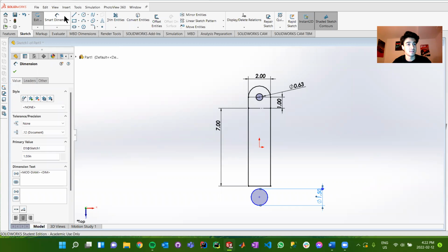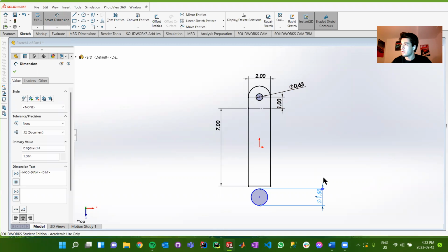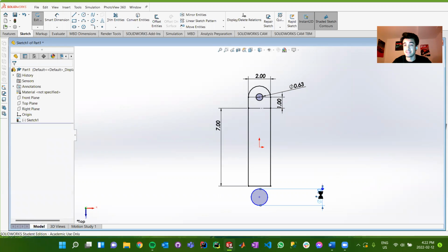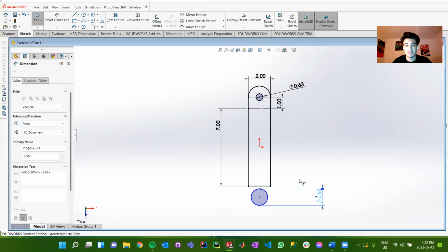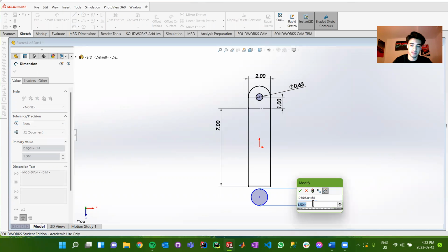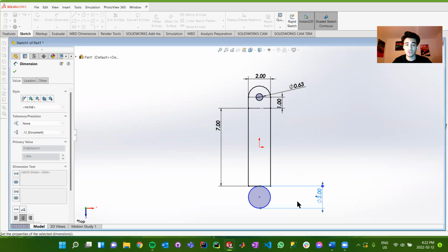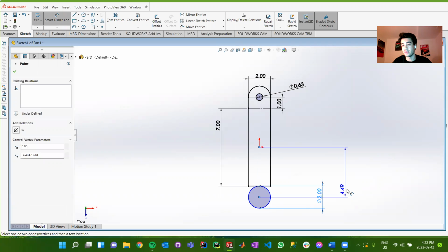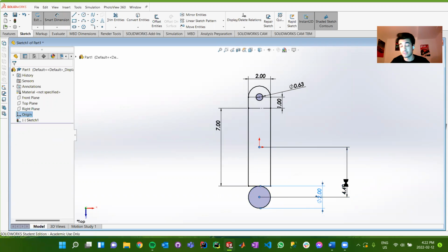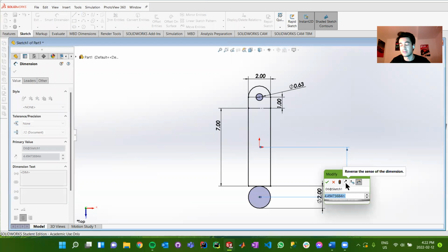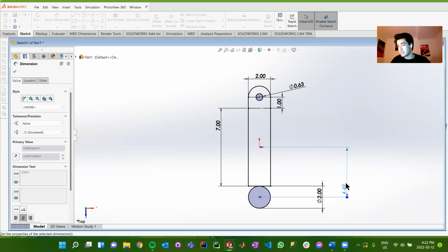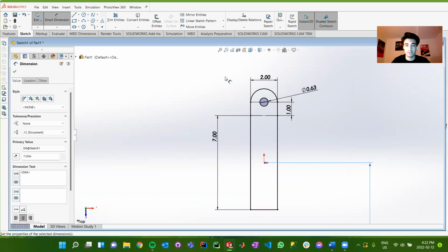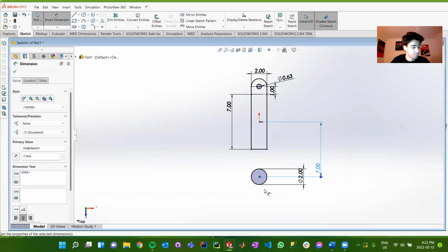Okay, perfect. Oh, but I've written it as a 2-inch diameter. My apologies. Here, we can change that. See, these are the struggles when you're working with multiple files at once. There we go. We'll make it 2 inches. And then I'm going to have this particular circle be 7 inches apart from our origin. And if you're wondering again where I got these dimensions from, they're from a part that I've already created. Usually in the engineering context, you have a set of dimensions and possibly even a drawing to refer to. For the context of this, I'm going off of my previous work.